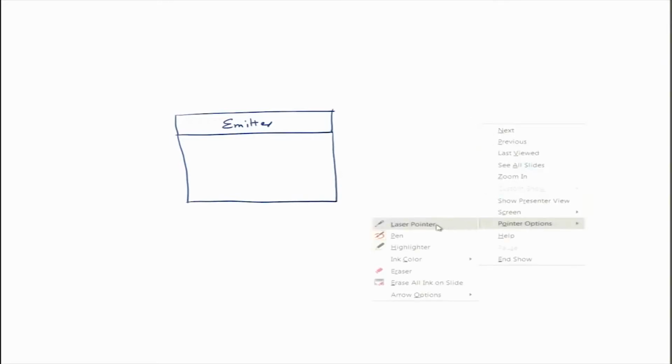A typical PN junction device: let us not talk in terms of emitter and base, that we will talk about when we learn about the silicon solar cell. We will just restrict ourselves to this being an N type junction and this a P type junction. Then you will have a front contact here, and on top you will have an anti-reflection coating.